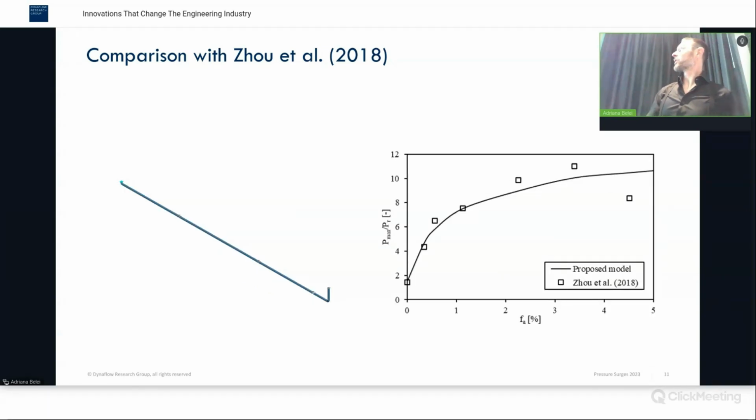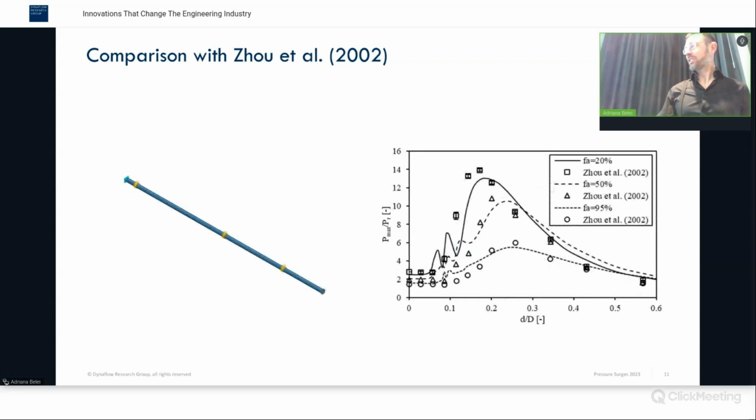This is another experiment, so here you can see too that it matches quite well. And then we have some more experiments here. This is another entire series of experiments where we change the diameter of an orifice with respect to the diameter of the piping, and you can get all these results. Now, one thing that is of interest here is that in order to match the actual results here, we had to make some modifications to the wave speed.